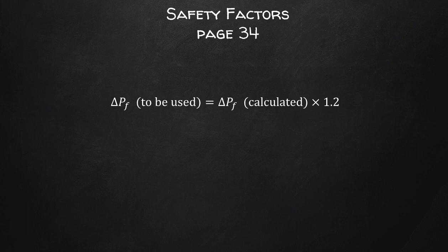Okay, so therefore, whatever you have calculated as a pressure loss across a system, just add to this 20%, so adjust by 20% increase, just to be on the safe side, so that when the system works slightly better than you had anticipated, your boss will pat you on the back and say, "Good job, it works."